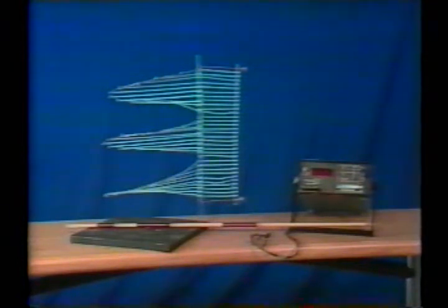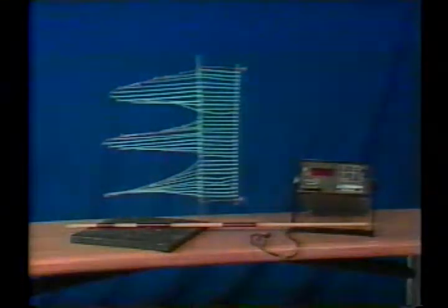Measurement of the BH characteristic of a magnetizable core provides the constitutive law that relates the magnetization density M, or equivalently the magnetic flux density B, to the macroscopic magnetic field intensity H within a material. The objective here is to observe the establishment of H by an imposed current in accordance with Ampere's law, and to deduce B from the voltage it induces in accordance with Faraday's law.